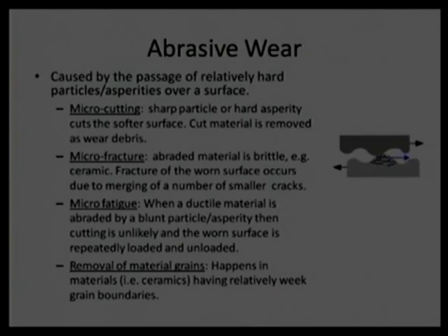So, it is going to cause stress on the surface again and again, and it turns out to be cyclic loading of the asperities, again and again load and unload, load and unload. That will cause some sort of crack formation in this asperity itself, or maybe beneath the asperity also.